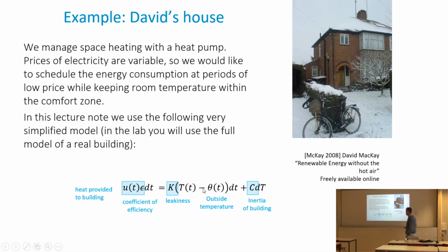So part of it goes away, and in this simple model it goes away proportionally to the temperature difference between inside and outside. If it's warmer outside, some of the heat gets inside. The house is being heated by the outside air. In the UK in winter, it's unlikely, so it's probably the opposite. Some of the heat you put in gets to the outside, so you're heating the country. That's the model.